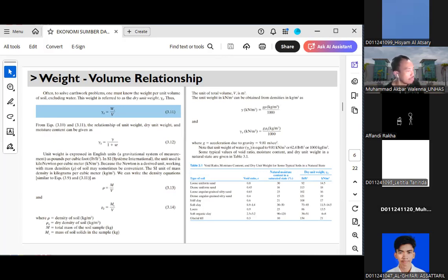Okay, so how are you going to use this table? Basically, this table shows you the soil type and how it affects the density and strength. So dense soil can definitely support more load, okay? While loose soils or soft clays are much weaker, they are more compressible. So you really need to be wary of those types of soils.